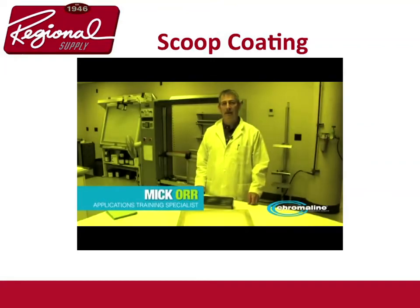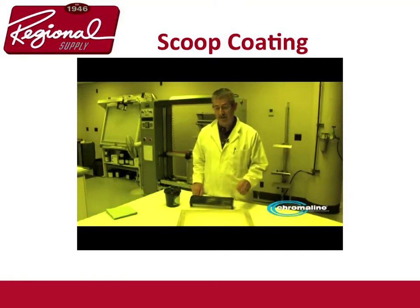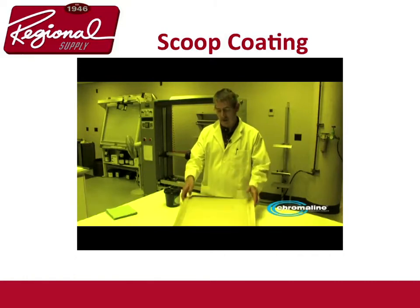Hi, I'm Bejar, Applications Specialist here at Chromaline. Now that you've seen how the diazo is mixed into the emulsion, the next step is to actually coat a screen. What you have to have is a clean screen. Get it completely degreased, ready to go, and nice and dry.